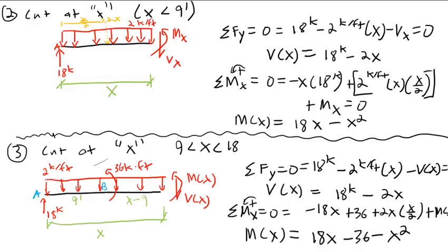Okay, yes? How would I know that I chose the wrong direction for the shear or the moment? Is it would be negative? Okay, how would you know if you chose the wrong direction for the shear in the moment? Well, if I'm cutting a beam like this and I have a cut that is on the right side of a member, I'm always just going to draw the moment as counterclockwise and the shear arrow as downward because that's positive shear. That is positive shear.